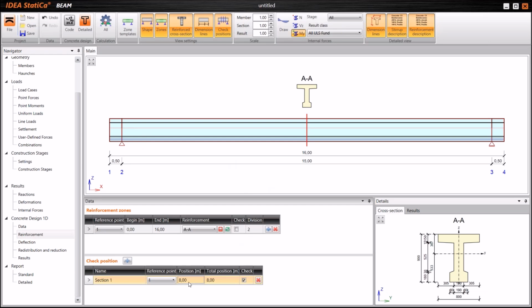both geometry and the loads which are applied, I will use 7.99 just to avoid the case that in the middle the program generated a very small point load caused by the tendon due to some effects which we cannot explain here. Now I avoid generating two load cases, two positions, one just before and one just after mid span.